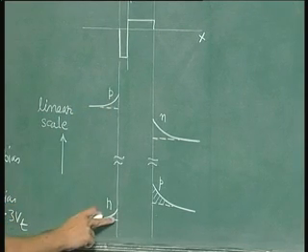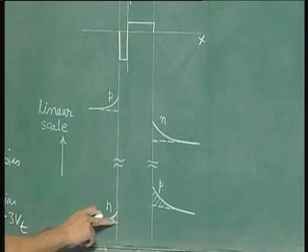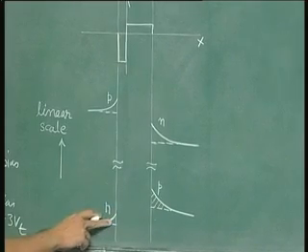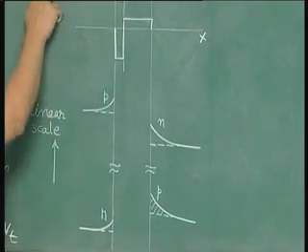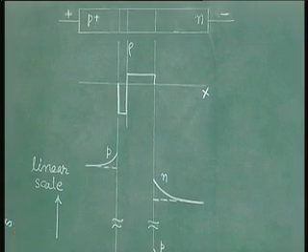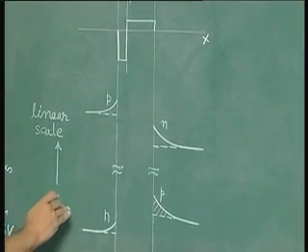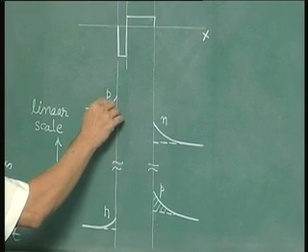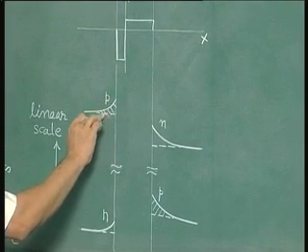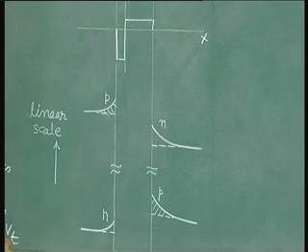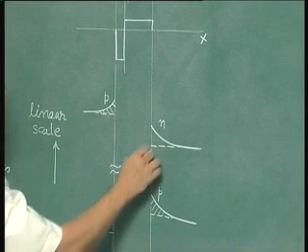So these are the injected electrons from the P side. To compensate for this, you have holes injected from the positive contact. So we will be shading the positive charges in the device. Okay, so these are the extra positive charges, excess holes on the p side. So dotted lines show the equilibrium condition.